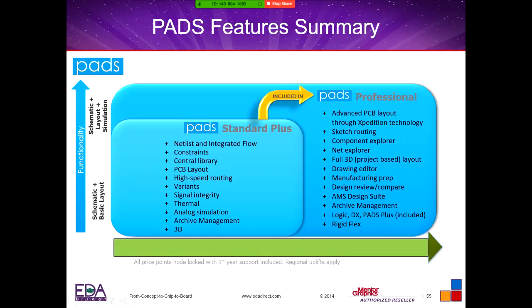Now one thing that I always get asked is, if PADS Professional is tied into the PADS tool, why aren't we using PADS technology? Well, what Mentor's trying to do is allow the Expedition technology to be used in the PADS world. So when you use the PADS Professional, you are not using PADS Standard technology, you are using Expedition technology. So it's a little more powerful. You've got the sketch routing, you've got the manufacturing prep. You're going to see a lot more capabilities within the PADS Professional tool. Rigid Flex will not be working with the PADS Standard Plus or the PADS Standard at this time. I'm sure that they're working on that, but right now it is working in the PADS Professional tool and Expedition only.